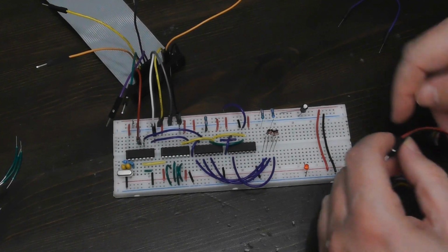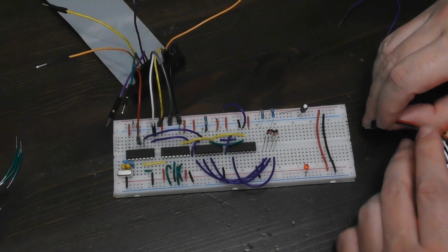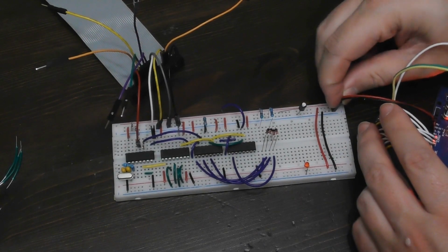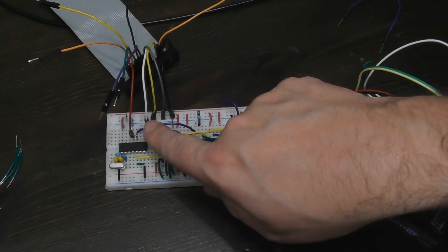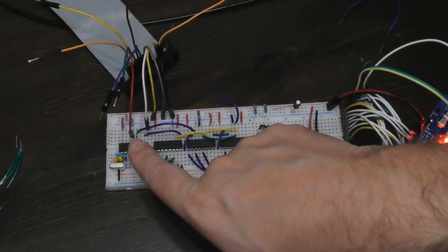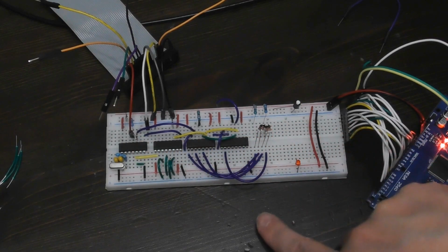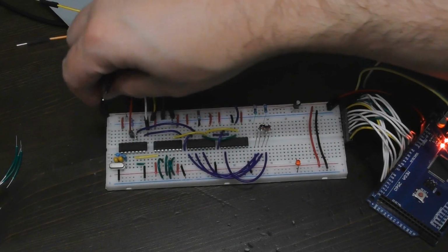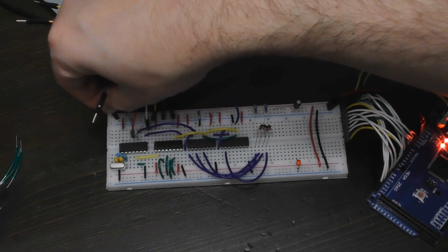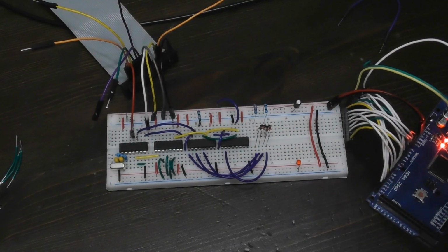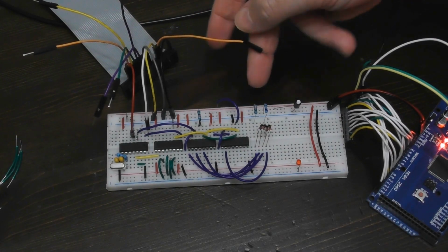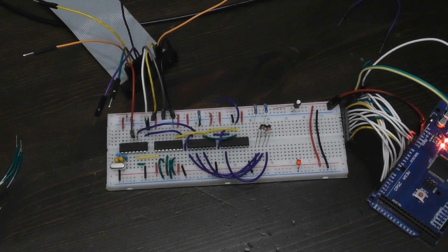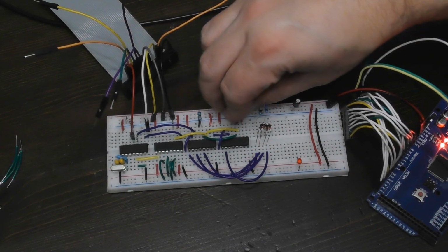I'm going to bring the Arduino back just to power things up, because that's how I've got that configured at the moment. So the disk drive is mostly still hooked up here. I haven't got it spinning at the moment. The read data line's all there, so that's all fine. It will be driving this circuit. I'm just going to step a few tracks just to get it off track 0, because track 0 is a bit corrupted on this disk. And was there anything else I need? The index hole I unplugged. I'm not going to worry about that. I don't need that. So yeah, I think we're good.